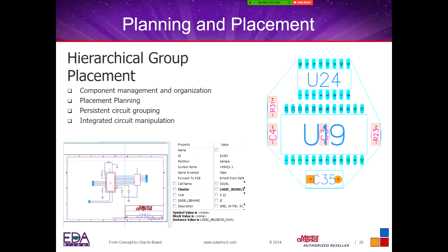It's going to be more of a hierarchical group. What it'll be is you'll be in the schematic and you'll set all the parts that you want to be associated with that, and then you'll just set up a cluster and give it a name. So this one's called reuse. These are all the components on the schematic, and you can see that they're all tightly inside this circle. That way we can now drag that reuse and pop it onto our board.